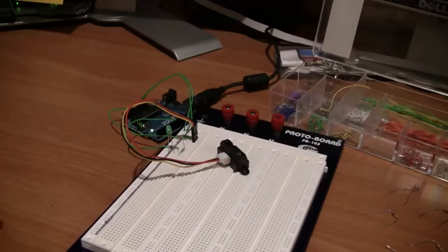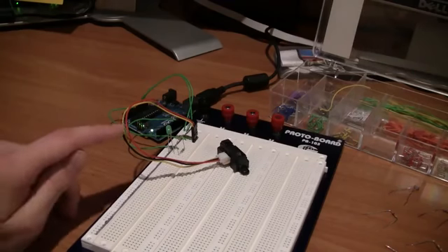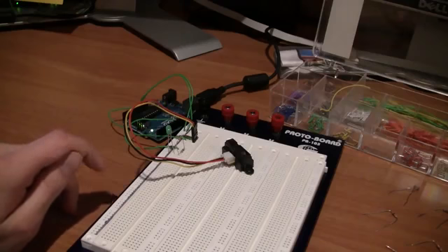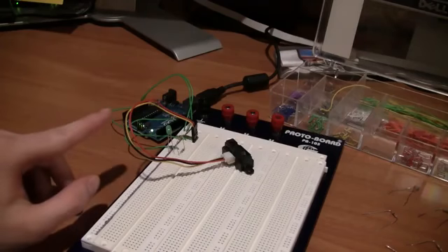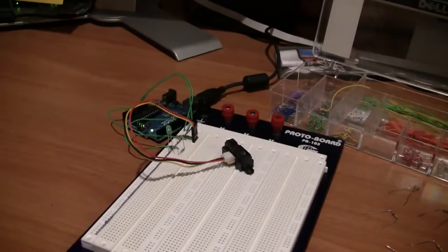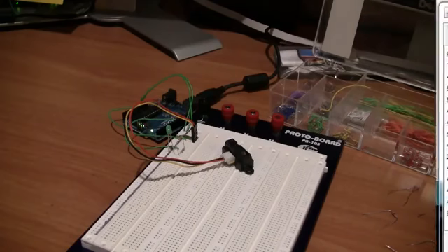All sensors that come like this will usually have 3 wires: a voltage wire, a ground wire, and a sense wire. The red wire, we give it 5 volts. Ground gets connected to ground, of course. And then the yellow wire returns a value between 0 and 5 volts that we can feed into the analog to digital converter in the Arduino and use it to measure a distance value. You'll often notice that these kinds of sensors will give you a broader range because they've already designed it to operate on the whole 0 to 5 volt range. You can also buy these sensors in 3.3 volt iterations and other voltage versions.